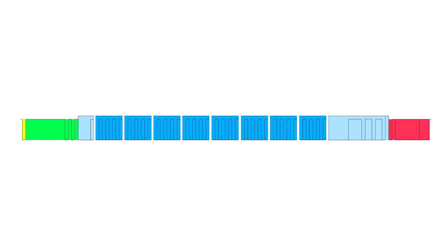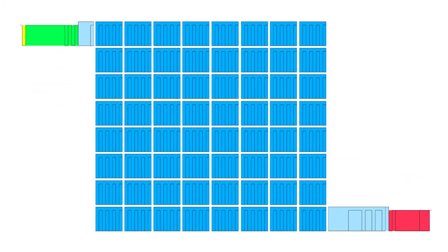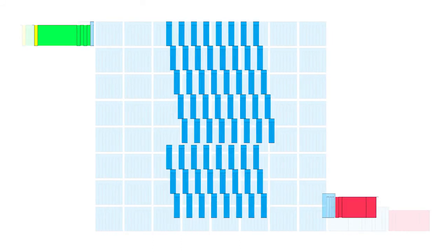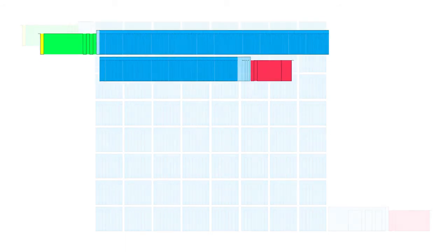CAN limits the number of bytes in a CAN frame to 8 bytes. In CAN-FD it is possible to have up to 64 bytes of data. By increasing the bitrate on such a large frame, it is possible to reduce the frame length considerably. The combination of CAN prioritized access to the communication and higher bitrate in CAN-FD makes it possible to combine advanced real-time performance with high data throughput.